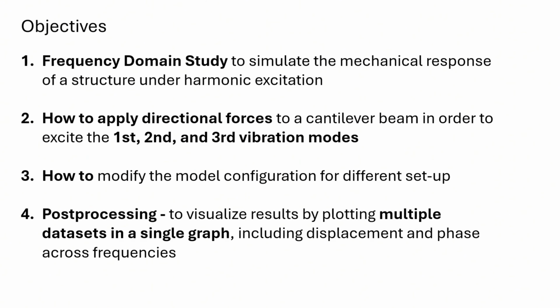In this video, we will cover the following topics. Frequency domain study to simulate the mechanical response of a structure under harmonic excitation. How to apply directional forces to a cantilever beam in order to excite the first, second, and third vibration modes. How to modify the model configuration for different setups. Post-processing techniques to visualize results by plotting multiple datasets in a single graph, including displacement and phase across frequencies.